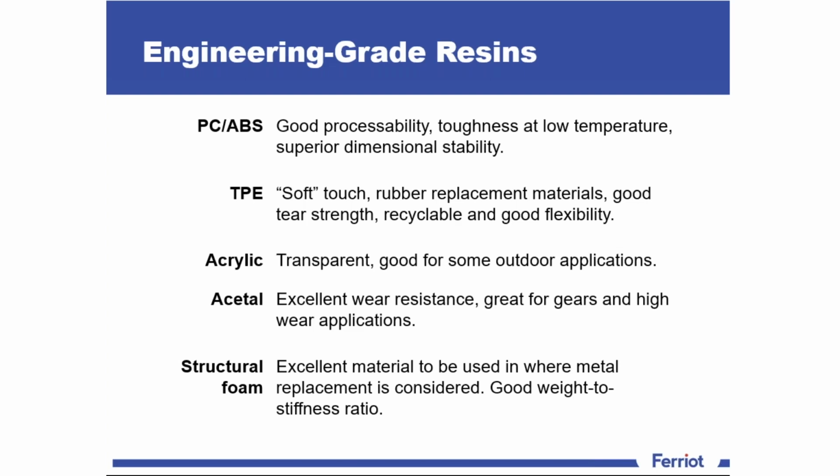And there's acrylics. Transparent, good for some outdoor applications. And acetals, excellent wear resistance, great for gears and high wear applications. And structural foam. It's an excellent material to use where metal replacement is considered. Good weight to stiffness ratio.